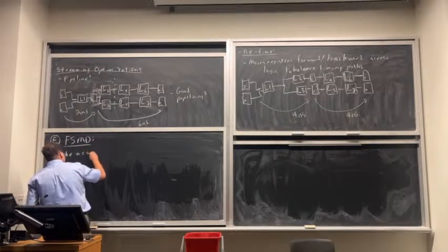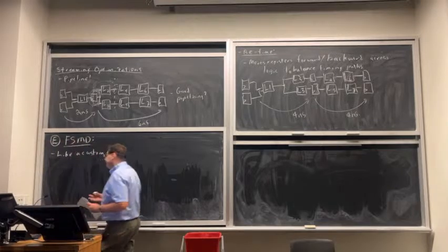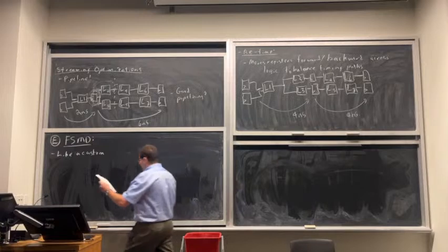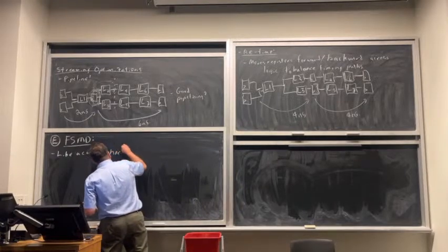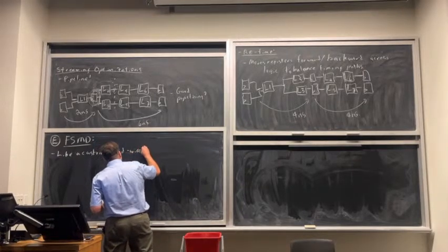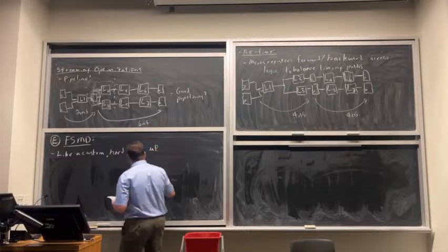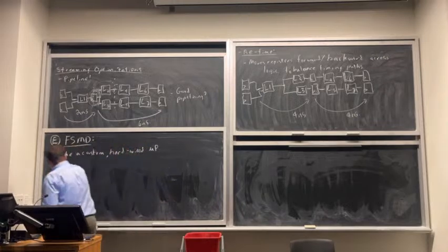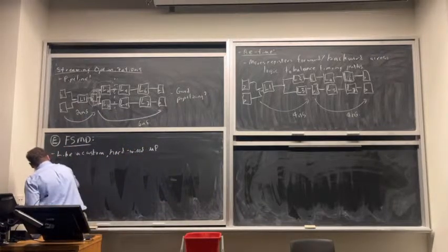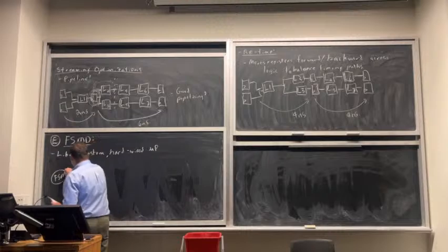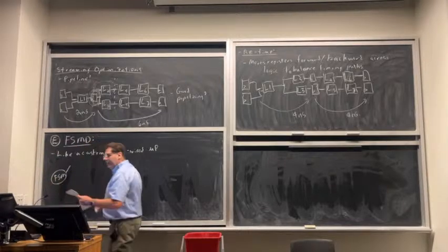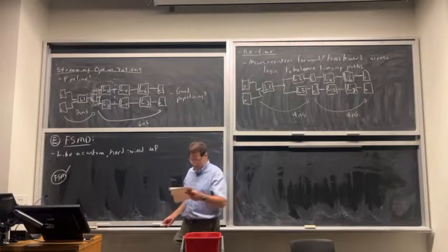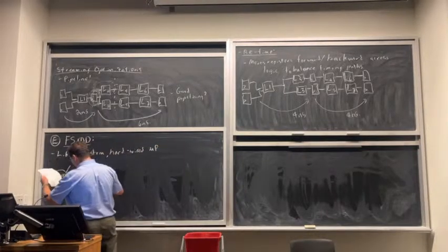It is custom hardware, but it has some similarities to a processor. It's like a custom, special purpose, basically hardwired microprocessor. It doesn't have an instruction stream. Instead, it's got a finite state machine, and that finite state machine is generating a bunch of outputs. Those outputs are controlling a data path. So instead of controlling a data path from an instruction stream, you're controlling it from a finite state machine.